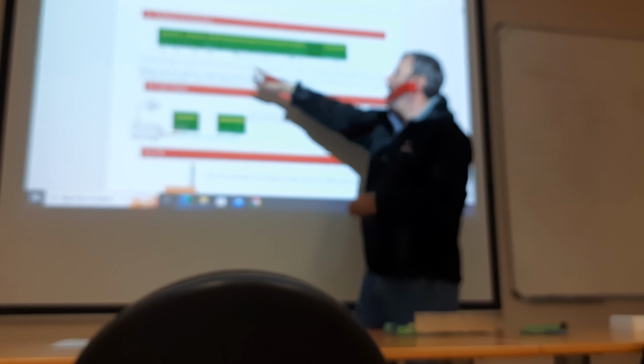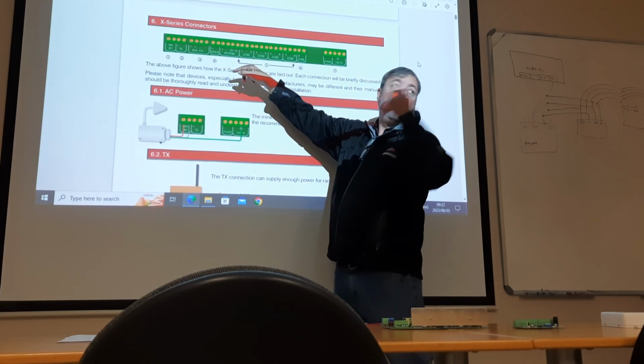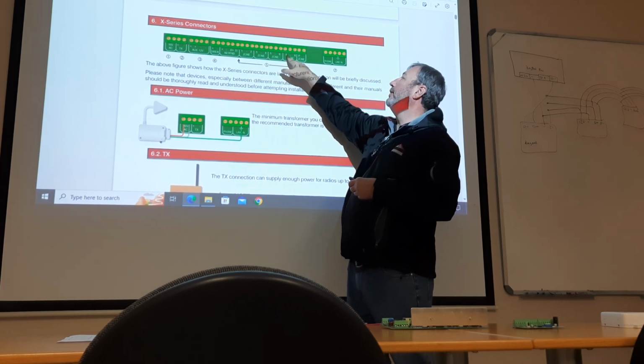And then your zones, like we said, zone 1, you see there. Obviously your keypad plus connection, positive and negative. But there is zone 1 and common and zone 2, so they share a common, like I'll show you guys on the board. And the same for 3 and 4 shares a common, 5 and 6 shares a common, and 7 and 8 shares a common.